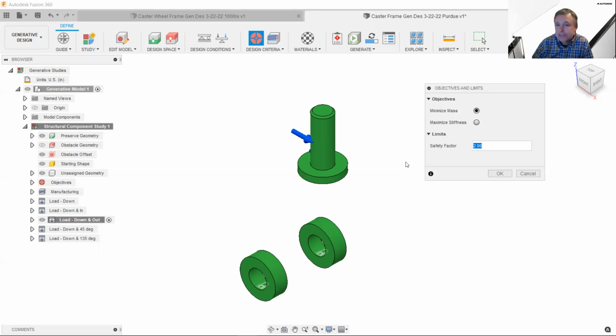Now, with a safety factor of 2, even though I designed it for 100 pounds, it'll hold 200 pounds. 201, it breaks, right? Now, this is what I also refer to as a love-hate relationship. So the higher the safety factor, the higher the mass, right? You need to have more mass in your model.